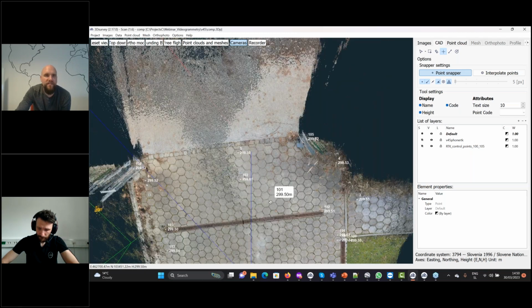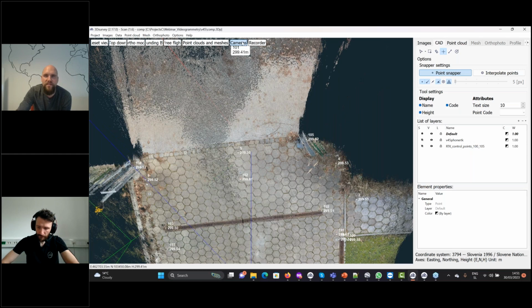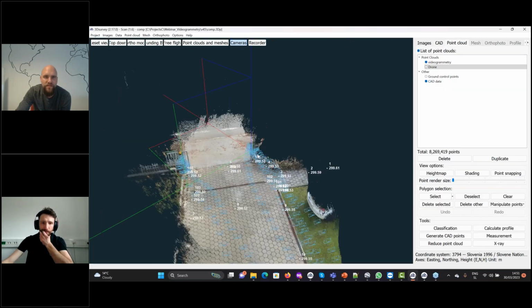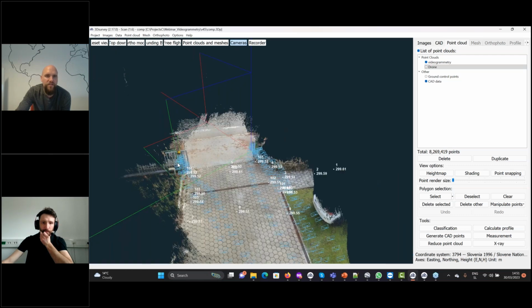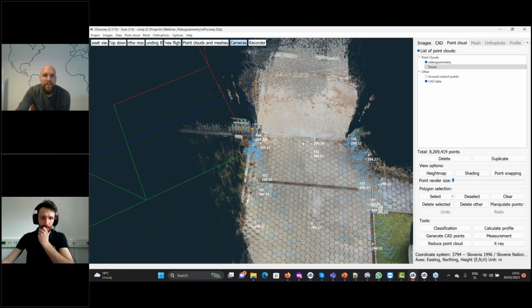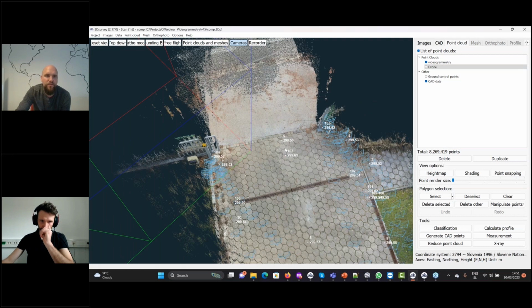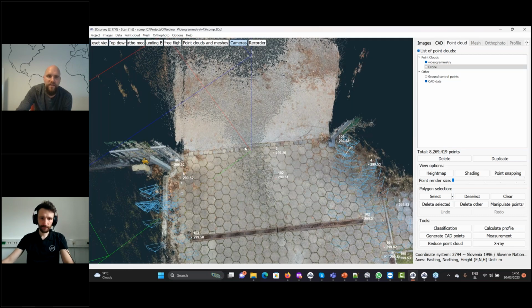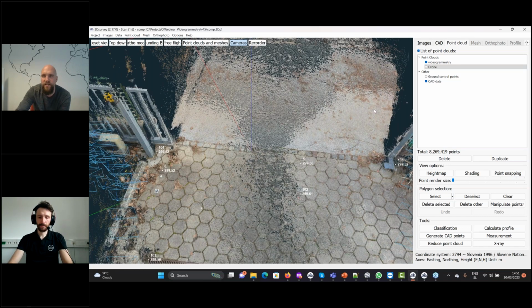And here, one thing that I did note that is interesting for me in this example, if we go into point cloud view, you see that I focused on this spot and on this spot here. Here in between, we had not enough overlap. You see that I obtained this kind of an error here, where there was less overlap.